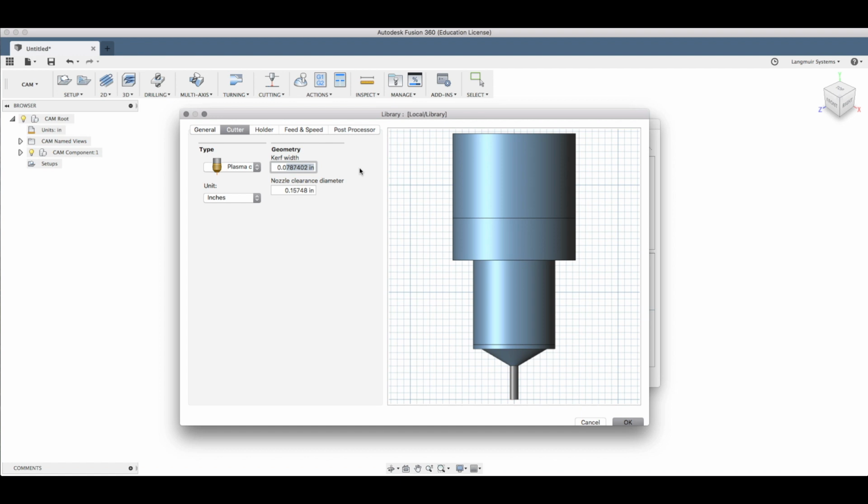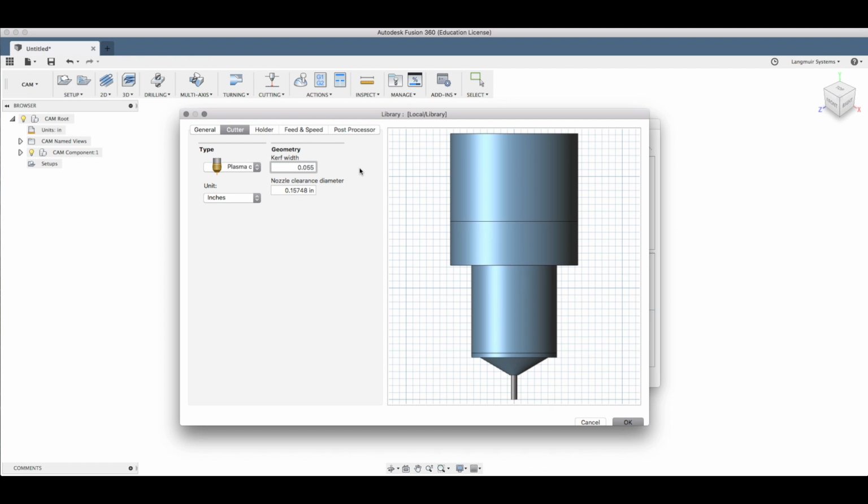If you're not sure, use a value of around 0.06 inches. For the Razor Weld 0.8 mm low amperage nozzle, we'll use a kerf width of 55 thousandths, or 0.055 inches. As the Crossfire is a 2-axis machine without any z-axis movement, we can avoid tip-ups with an accurate nozzle diameter in conjunction with the Keep Nozzle Down function. For our cutter, the outer diameter is conservatively 1 inch, but this may differ for you.